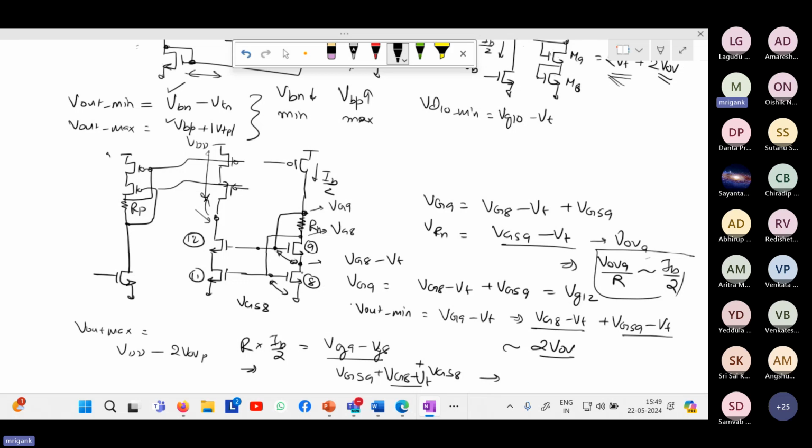So in the 32 nanometer PTM, are you able to simulate for different corners? Do they have the model for different corners? Slow, fast? No, sir. 32 nanometer PTM does not have that.